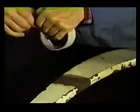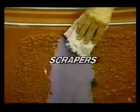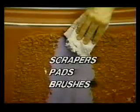Before applying paint remover, be sure to mask surrounding areas which may be damaged by the stripper. These areas include windows and canopies, all plastic parts, rubber hoses and tires, and all composite surfaces. Apply a thick continuous coating of the paint remover and leave it there long enough to wrinkle and completely lift the paint. Scrapers, pads, or brushes can be used to remove stubborn paint. Use more paint remover as needed.